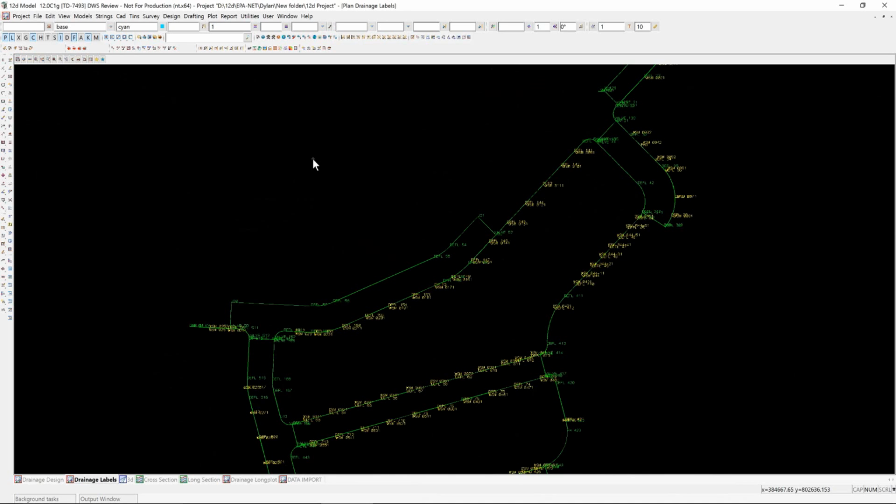One advantage of that is when you try and run it, it'll tell you where there are any disconnects and allow you to go and find them immediately and reconnect them. So where you have a line that doesn't have, where another line is coming in but there's no manhole on the parent line, you can create the manhole, snap to that. Where snaps missed by 50 millimetres or something because they were just drafted, you can create those.